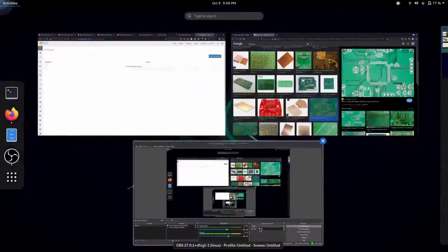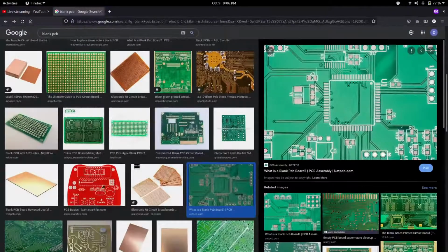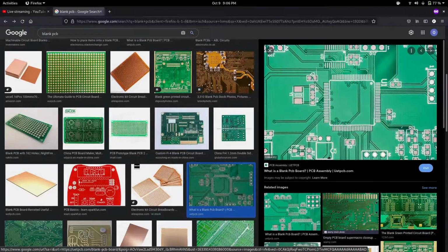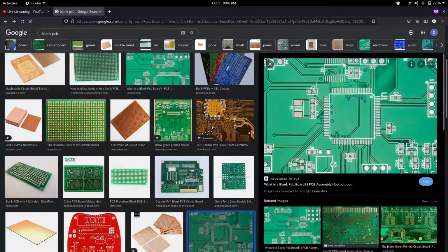Now, why are they so hard to design? First of all, if you've got all the components in different places, you can't cross connections, right? At least not in a single layer, because then they would be electrically connected to each other and you might not want that. So you have to route your connections so they don't hit each other unless you want them to. Also, printed circuit boards can have multiple layers if you need to have signals go above and below each other.